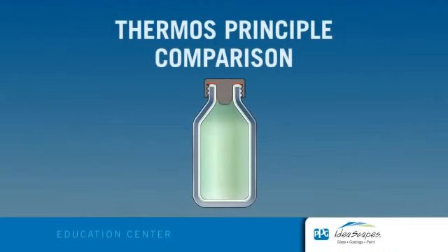To use a simple analogy, low-E glass works the same way a thermos does. A thermos has a silver lining, which reflects the temperature of the drink it contains back in. The temperature is maintained because of the reflection that occurs, as well as the insulating benefits that the airspace provides between the inner and outer shells, similar to an insulating glass unit. Since low-E glass is comprised of extremely thin layers of silver or other low-E materials, the same theory applies. The silver low-E coating reflects the interior temperatures back inside, keeping the room warm or cool.